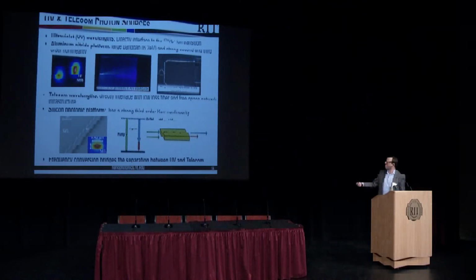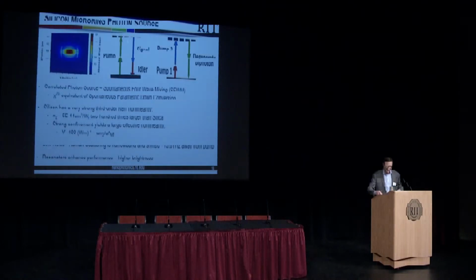So in terms of the silicon photonic platform, I haven't gotten into the nuts and bolts of it yet. So basically what you have is a waveguide, just a rectangle of silicon, and all you do is put a laser in there. I just want to reiterate that point. You could essentially just take light out of the internet, send it in here, and you're getting photons essentially for free coming out of this chip. So here is that again, just with a little bit more technical details. So the light in the silicon waveguide essentially looks like this. This is called the optical mode.